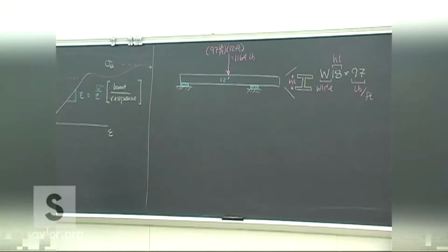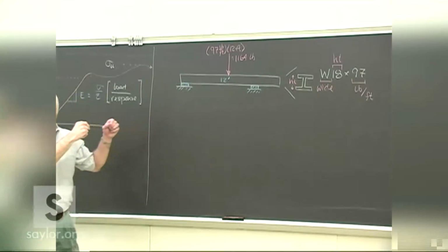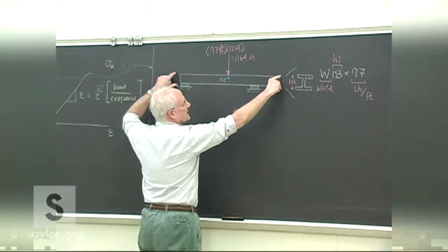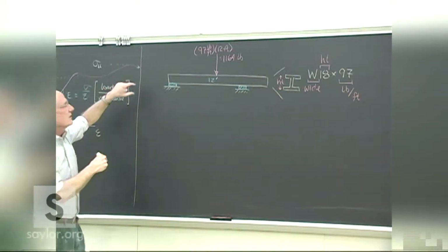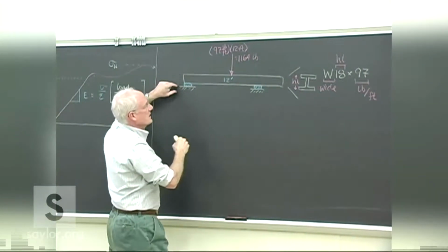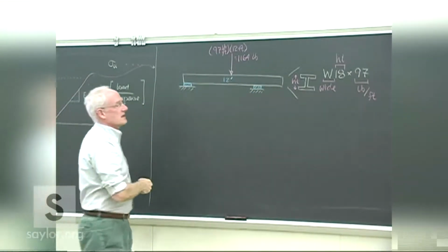One, it absorbs any of the up or down forces, just to give the beam a little bit of flexibility, but it also allows the beam to change shape thermally because of the change in temperatures from use. As a beam like this might go through the year, the beam can change in length, and these shear pads can absorb that.